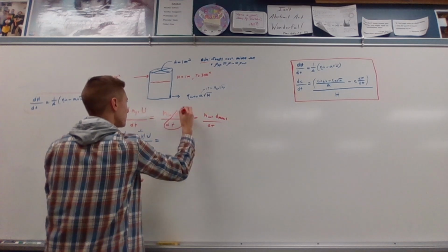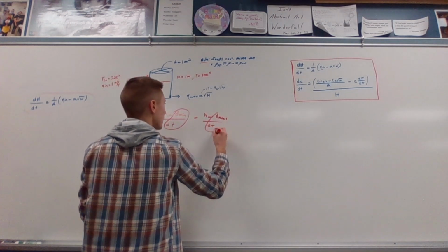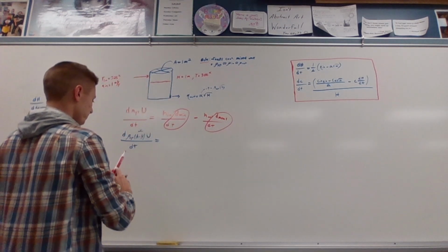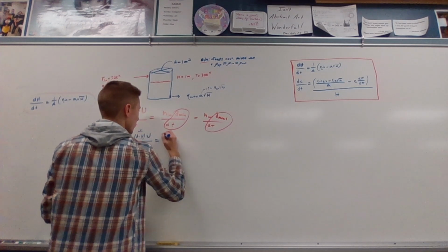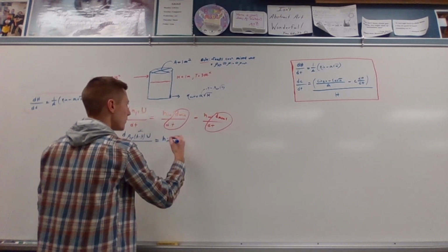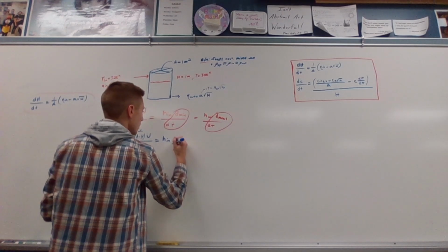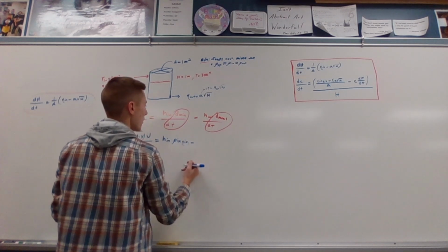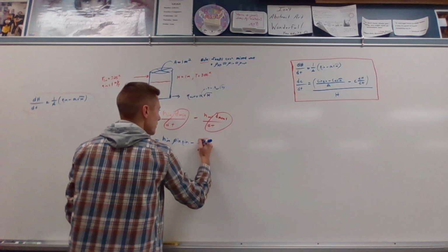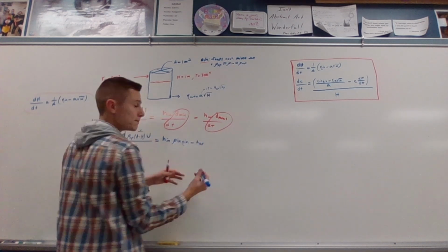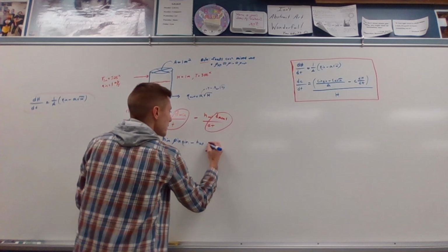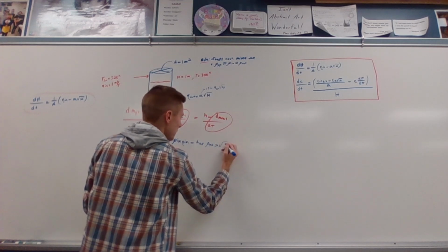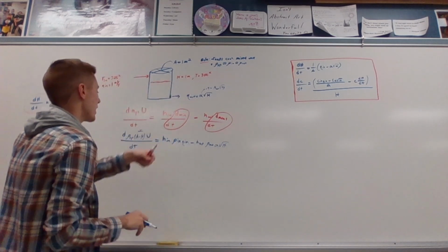term here and this term here we can go ahead and rewrite. That's the same thing as, sorry, H_in doesn't change yet, or enthalpy in. You can write this term as our density in times our flow rate in from before, and rewrite this as our enthalpy out times our density leaving times our flow rate out, which is alpha times the square root of our initial height of the water in the tank.